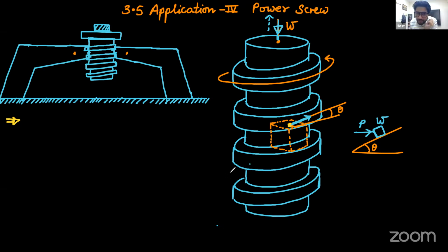Here means where? Actually, there is some controversy because the screw is sitting on an inclined plane starting between the inner radius of thread up to the outer radius of thread. We assume that the whole blue screw is kept over that orange internal thread inclined plane.